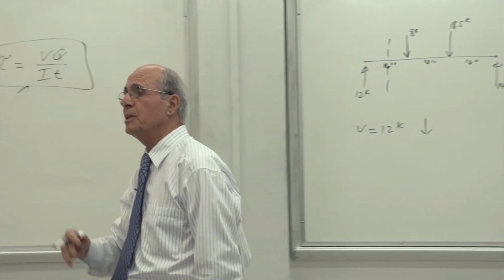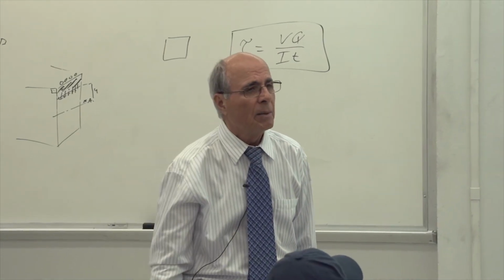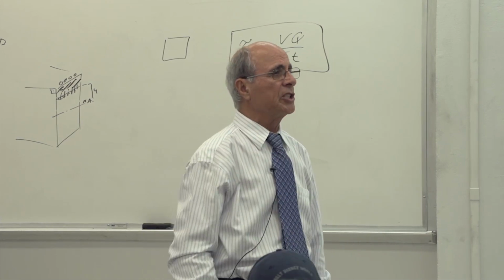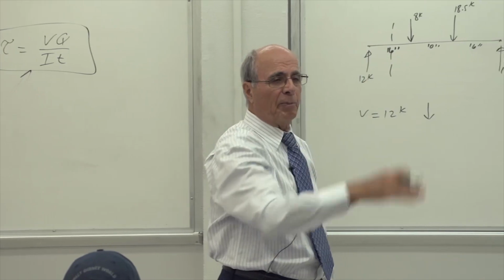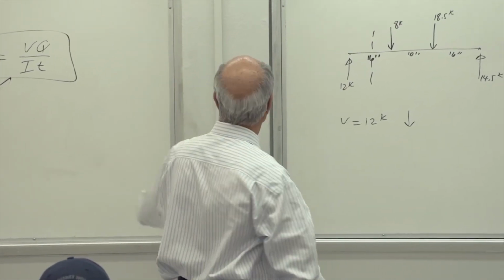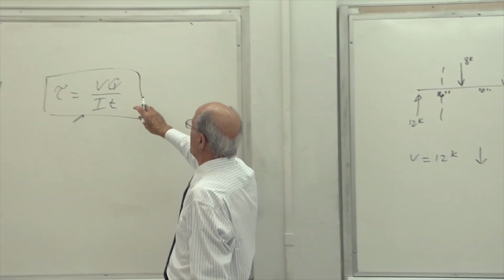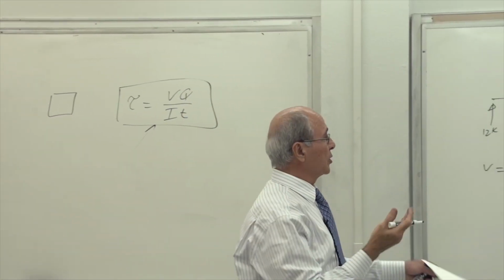You already answered me. That distribution is with Q, so it is a parabola. It is not a straight line. It's not like moment. The moment was 2 lines, one going up, one going down. This was linear. Is that correct here? Here is a parabola because Q actually is area times distance. Everybody see that? Yes? So now let's calculate that.